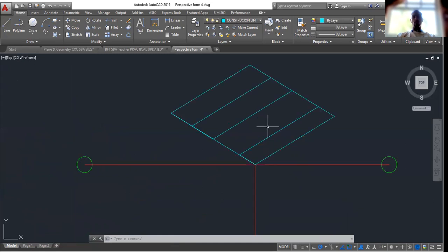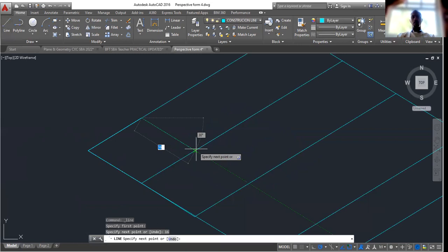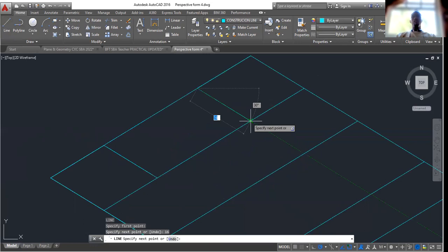All right, so going back, let me start from here. 16 millimeters. I come down this way until I see the X pop up, the intersection object snap. I click, enter, press enter again to draw a new line. And this time I'm going to start from the corner here, 16 millimeters, enter, and I make sure I have the correct 30-degree angle, and I click here, and that would be my top.